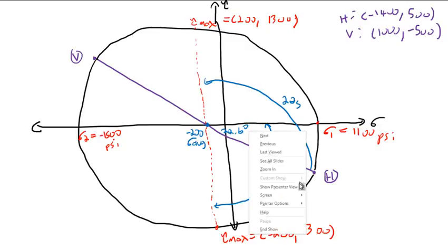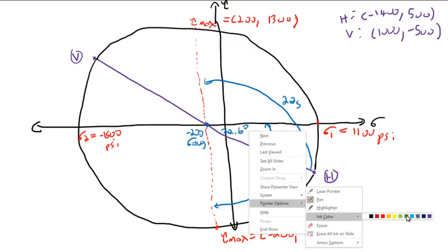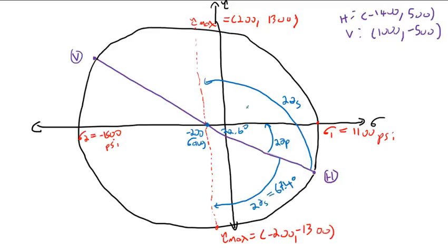Then to point A, we're looking at plane A, what we asked for at that one point. It's going to be up here. This is 614, 1013. But we were actually told the angle. So we found this after we found the point and the angle. We were just told the angle, and it is 2 theta A equals 73.7 degrees.